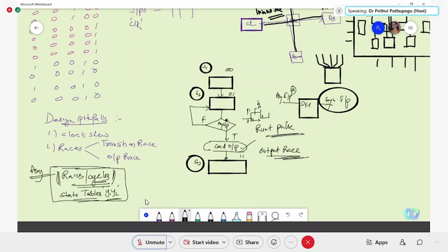Why we call this an asynchronous input is that it is with respect to the system clock we are using. We run this flip-flop with reference to the system clock. That synchronizes the asynchronous input so that it appears at the moment of the clock going from 0 to 1. This will be synchronized with the other elements of the design.